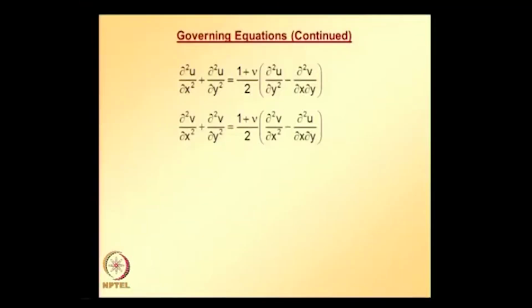And similarly, starting with the second equilibrium condition, which is the equilibrium condition in the y direction, the sum of all forces in the y direction is equal to 0. Applying that condition we get the second equilibrium equation, and following similar steps as we did for getting the first equation shown here, that is expressing stresses in terms of strains and strains in terms of displacements, and doing a couple of mathematical manipulations, finally we arrive at the second differential equation, which is also a second order differential equation.